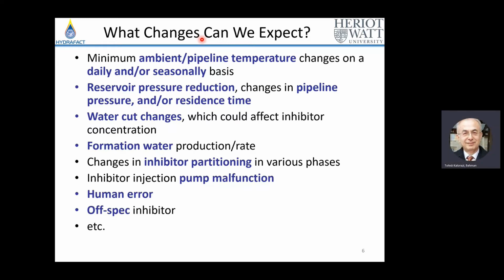Also, after production for a while, reservoir pressure will be reduced. That will affect the pipeline pressure or the residence time, that is, how long the pipeline will be in the hydrate region, or how long it will take for the fluid to pass through the pipeline.